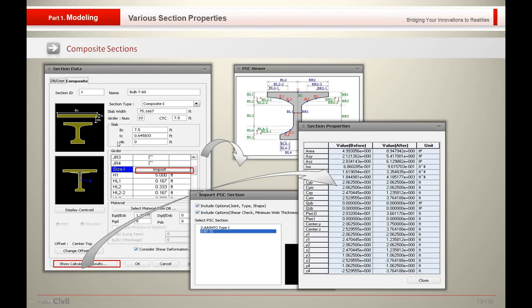Okay, so also you can control, like in composite sections, usually the problem that we face is that while doing construction stage, we first define the girders over the bearings, okay, and after some time we lay the formwork for the slab, then we pour the slab over the formwork. Even when the slab is present in its wet form, we do not consider the composite action there, okay. So we consider the composite action only after the slab attains its green strength. So we can actually control this in MIDAS Civil. You can control when to activate the composite section, when to activate before composite, when to activate after composite. So you can see the properties here, like before composite and after composite action, okay.